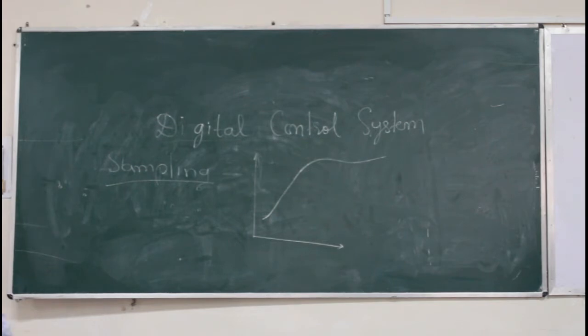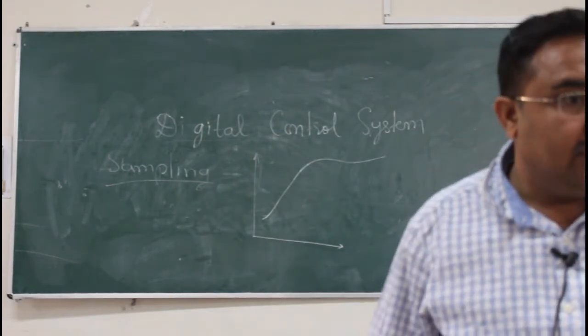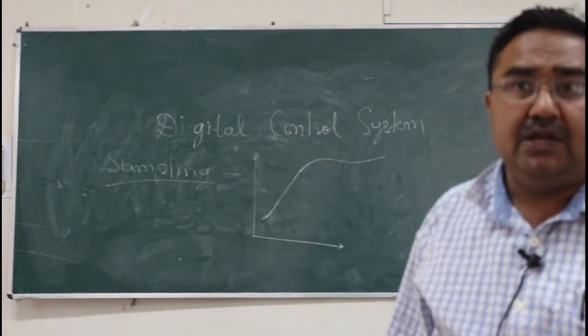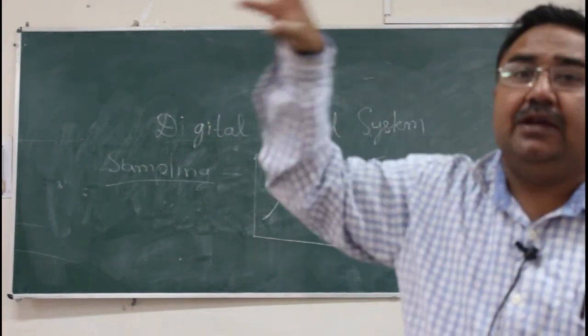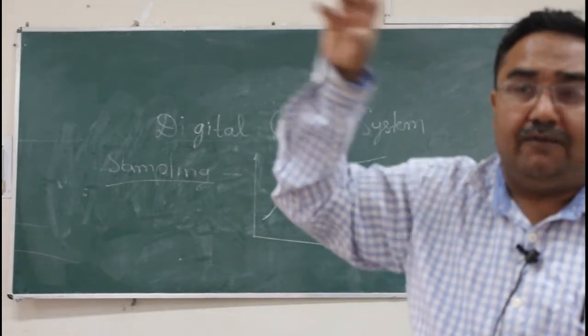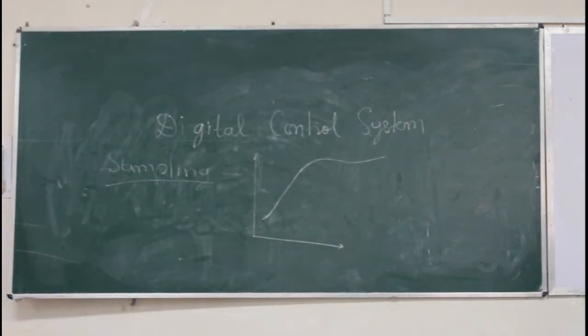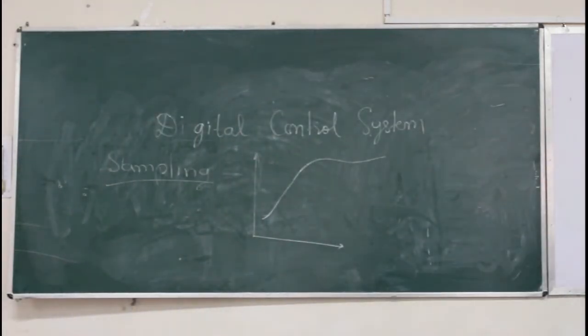Okay. Similarly, a tubelight manufacturer like Philips, whose production is near about 1 lakh per day. Will it send all 1 lakh tube lights? It will send particular samples. 1000 samples are sent to the ISI. ISI will check whether this much luminance is there, whether it sustains this much over voltage or not, what is the quality of the coil, of the choke, of the glass material, of the fluorescence material, and what are the materials of the connecting metals. Is it clear? So after everything is checked for 1000 samples, it gives a certification: yes, now you can put the ISI label on every product.